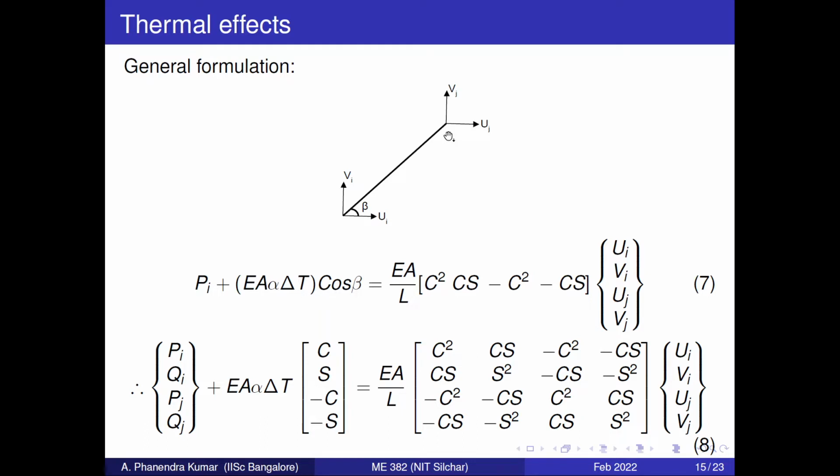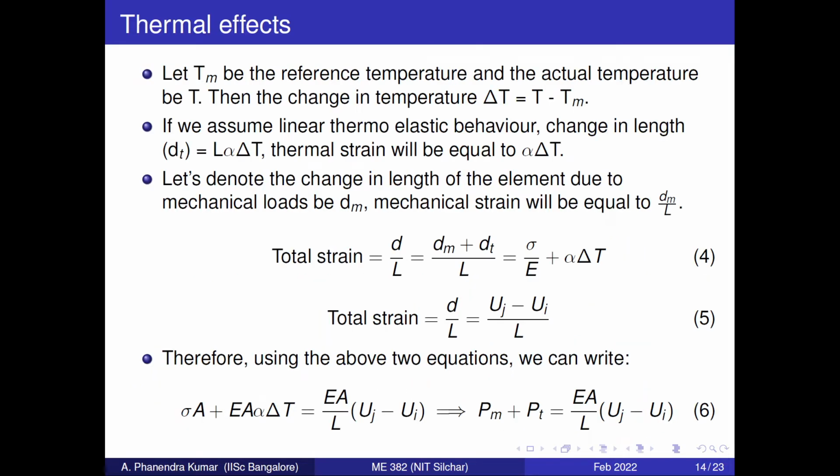If the actual length is L, and it is increased to L plus 0.2 mm, then what we are going to do is equate that 0.2 to this L alpha delta t. That extra 0.2 term will be equated to L alpha delta t, and we can obtain the effective delta t for that particular change in residual stress.